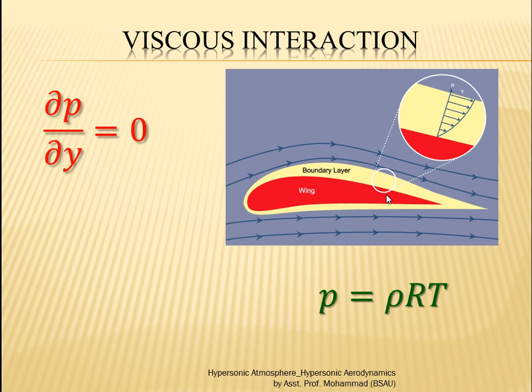The reason was we have to have some kind of high density to compensate the flow and maintain the continuity equation, the conservation of mass. But in this region, if you look at the microscopic level of the boundary layer, the density comes down because the temperature is very, very high. So we get a very thin flow here.